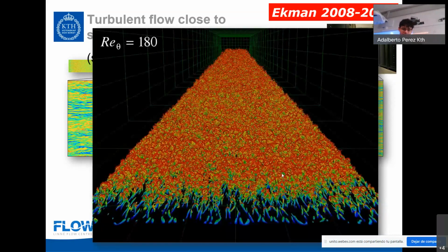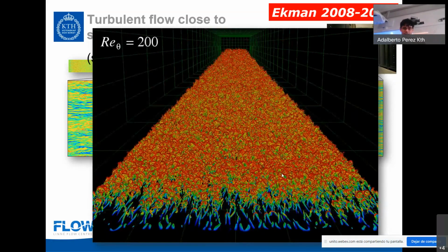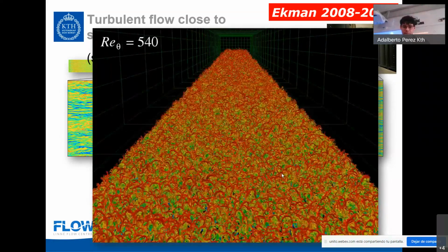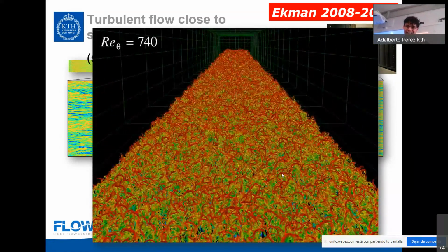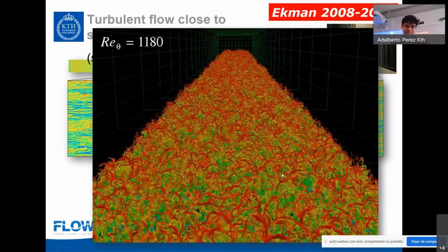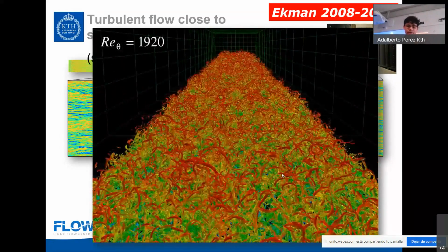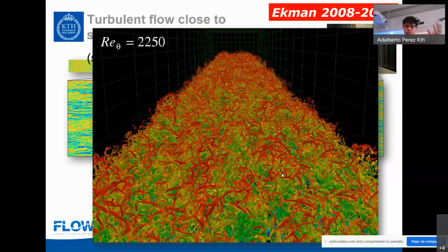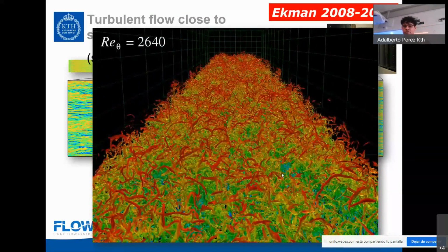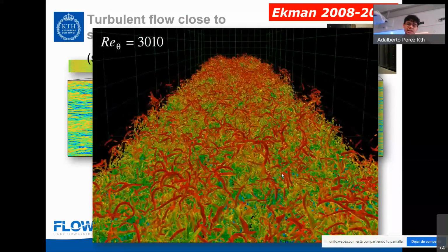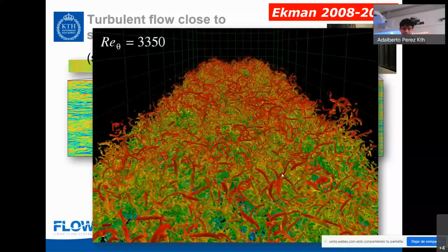And here there's a visualization of turbulence where we see these structures happening in the domain. And again, I have said this many times, but I keep saying it. We need our mesh to be able to solve these small structures because they are very important for the turbulence, for the friction and all these things that produce in the end drag and air resistance.